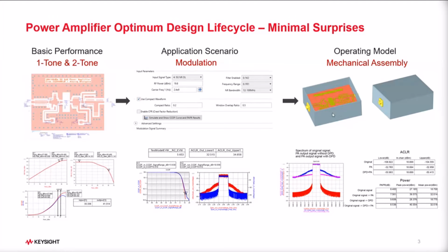In exactly the same manner, if you design a PCB and it tests okay, but once you put it in a cavity, things start to change a little bit. So eventually, this is your operating model. This is how your designed circuit will get housed, so you need to ensure that your circuit is working in a final assembly level situation.